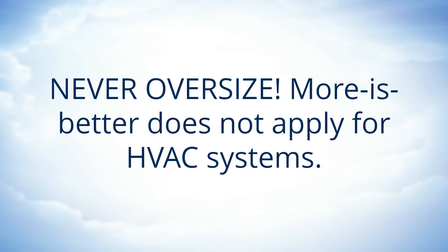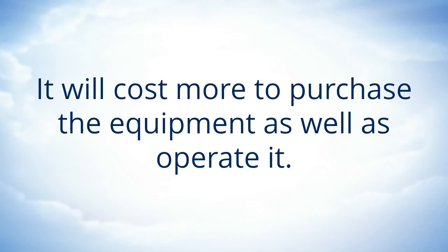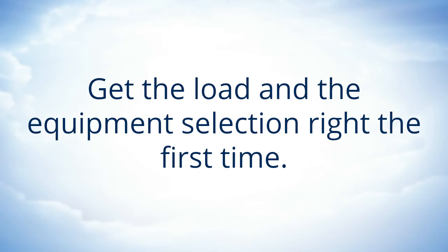Never oversize. More is better does not apply for HVAC systems. It will cost more to purchase the equipment as well as operate it. Get the load and the equipment selection right the first time.